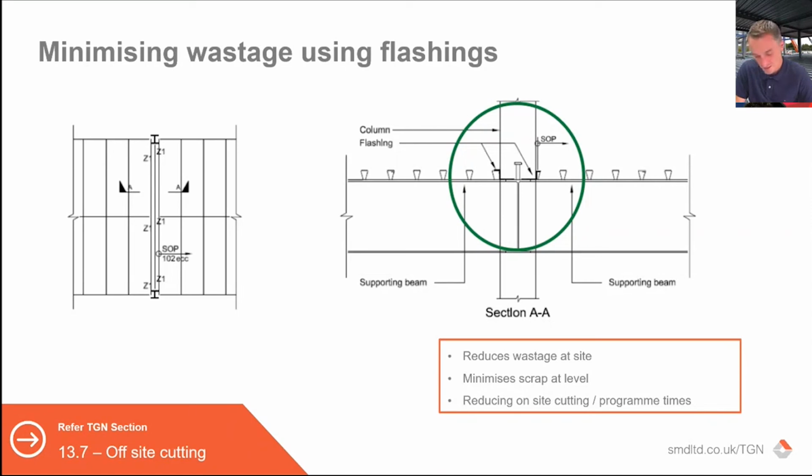It depends largely on the flange thickness, which is naturally going to protect you against the issue. The thicker the flange, I'd need to have a look at some examples because it does come down to the climatic conditions on the day, the weld settings the welder's having to use, what amperage he's having to use, and what timing he's having to use for that weld. Because the longer the time and the higher the amperage, the more it'll impact the steel.